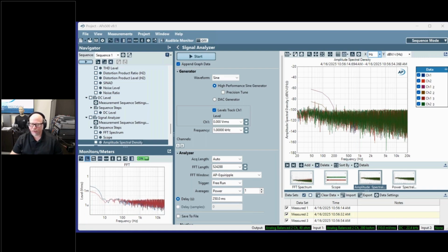The output load reference refers to the dBu generator unit. dBu is a little bit archaic because it implies that you're testing a 600 ohm terminated circuit, and the generator reference refers to that. What is the generator's source termination? Very, very few people actually change their generator source termination, so I would recommend leaving that alone.